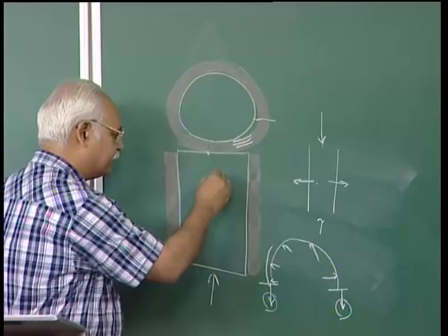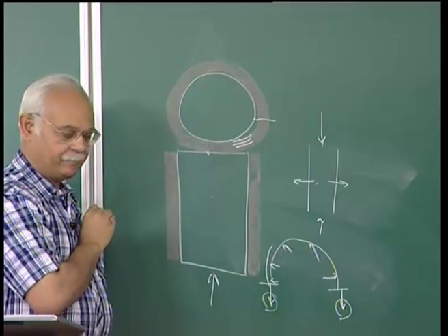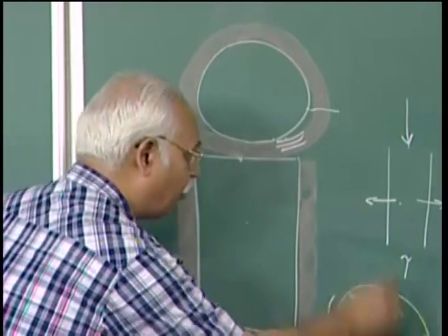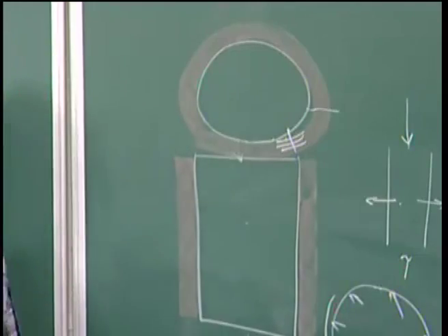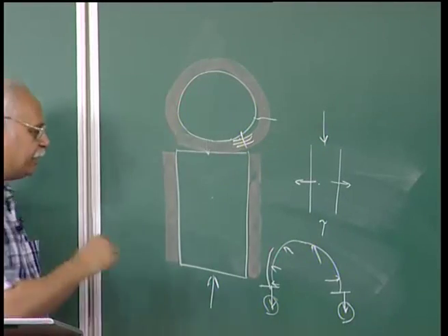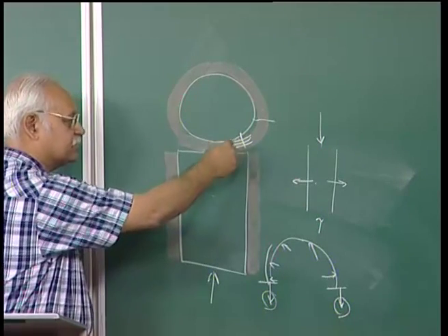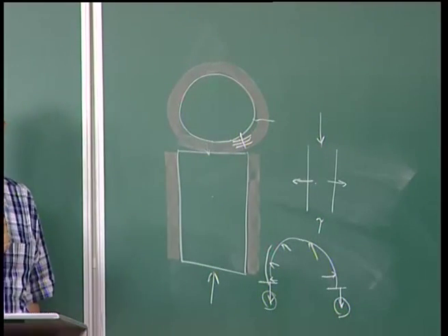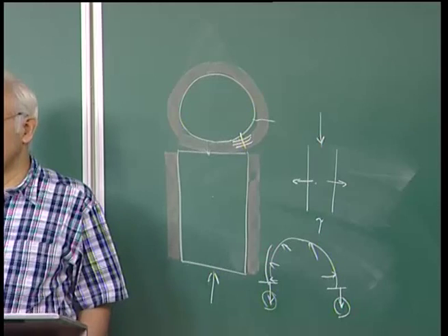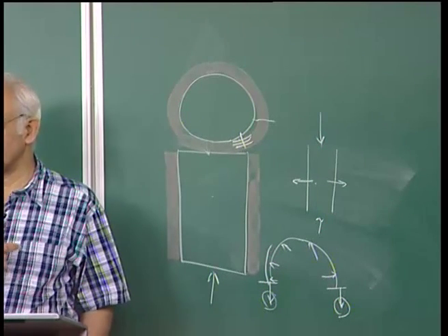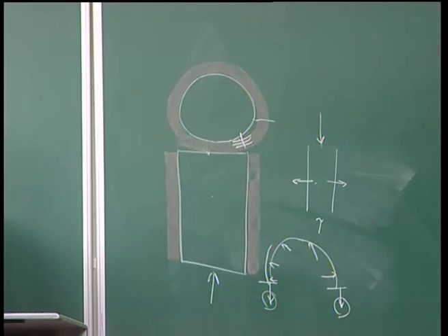In order for the concrete to fail, all these sheets must fail. So, this is one of the methods where FRP sheets are used in several layers wrapped around concrete columns to increase the load carrying capacity of the deteriorated reinforced concrete column.